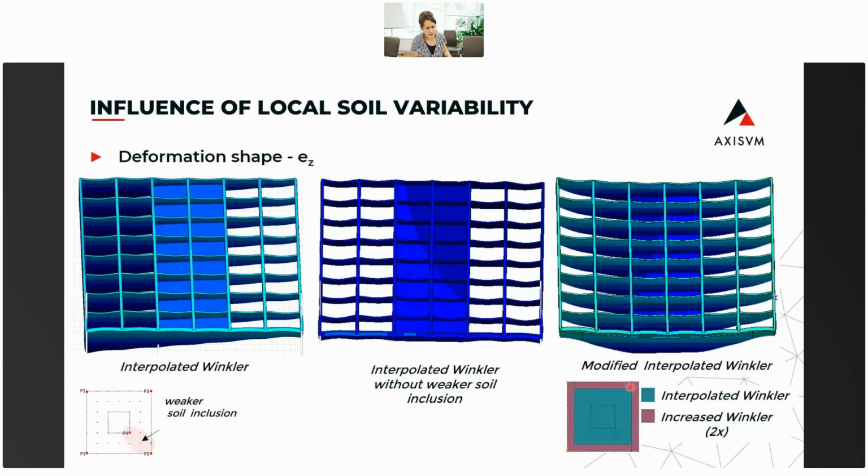In this case, I have again modified the interpolated Winkler model. I adjusted the soil stiffnesses around the edges. I increased them and used the interpolated Winkler stiffnesses in the middle. Now the result is again closer to the expected one.